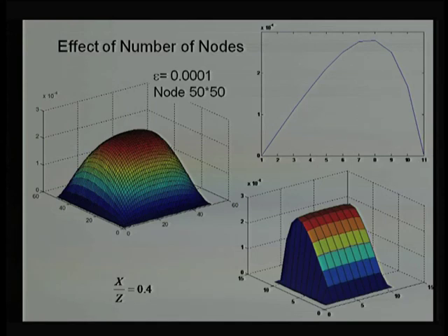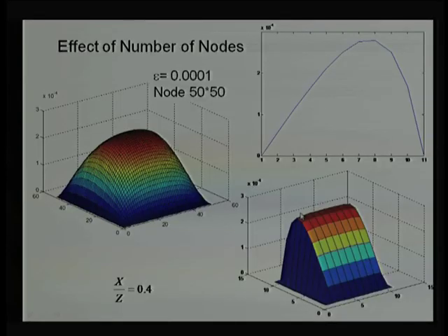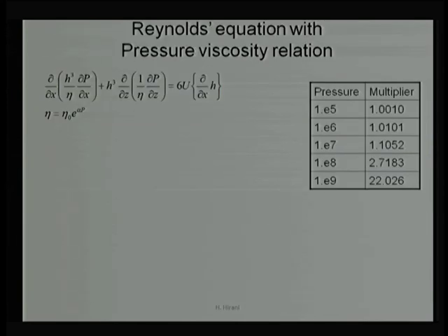That is why, when we have this kind of situation, we require simultaneous solution of equations. In those situations particularly, anything which is known to us is going to help us a lot. Like in this case, the hybrid approach is giving a good pressure profile to us. Better we use that pressure profile as the initial pressure profile for the finite difference method, so that we can achieve overall good results.